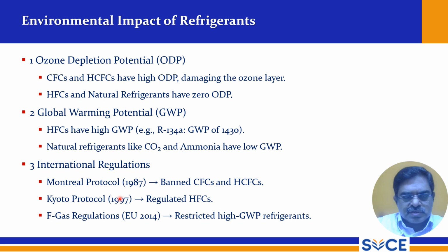International regulations. So Montreal Protocol, it is 1987, banned CFCs and HCFCs, whereas Kyoto Protocol that came in 1997 has the regulations on HFCs, and F-gas regulation, that is EU, that is European Union, 2014. They have stringent norms on refrigerants and restricted high GWP refrigerants. They have made a lot of changes in refrigerants.